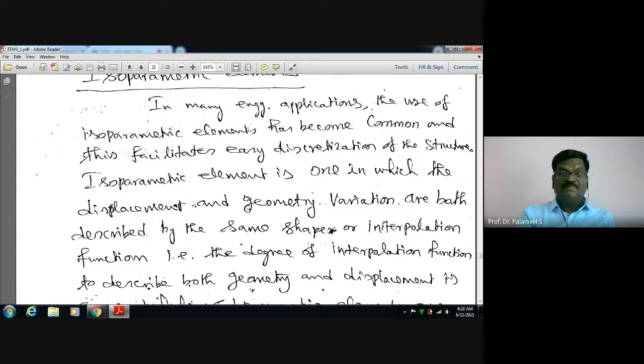That is important. In many engineering applications, the use of isoparametric elements has become common, and this facilitates easy discretization of the structure. Why? The structure can be easily discretized if you use triangular, rectangular or quadrilateral elements. That is why these isoparametric elements are most widely used. An isoparametric element is one in which the variation of displacement and the variation of geometry, that is coordinates, and the field variable inside are described...